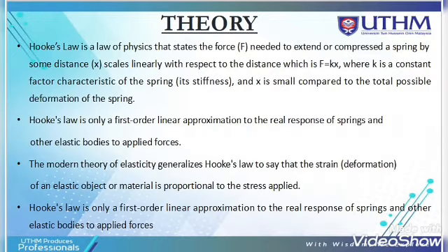Today I would like to present the theory and conclusion of Case Study 3. The theory behind Case Study 3 is Hooke's law, a law of physics that states the force needed to extend or compress a spring by some distance x scales linearly with respect to that distance: F = kx, where k is a constant factor characteristic of the spring, its stiffness, and x is small compared to the total possible deformation of the spring.